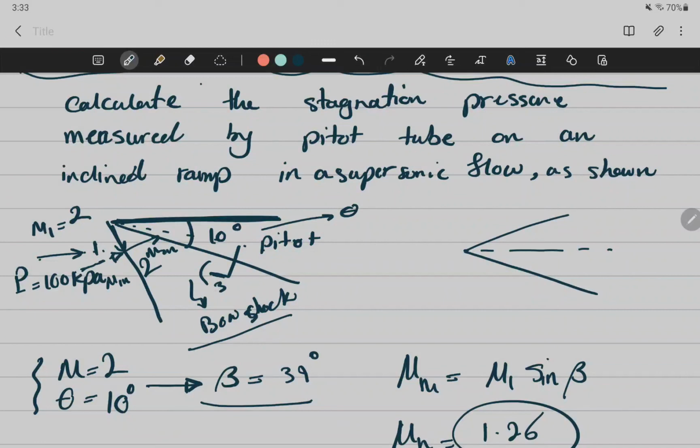Okay, so the M2 is flowing directly out of the pitot tube. Yes. Well, that doesn't have anything to do with the direction of the shock. That's just where I was getting confused, why we can use M2 for the pitot tube. No, because M2 is still supersonic, right? And there is an obstacle in front of a supersonic flow, so you will see a shock formation. No, that makes sense now. That's just which direction it was in. Yeah, it's moving in this direction.